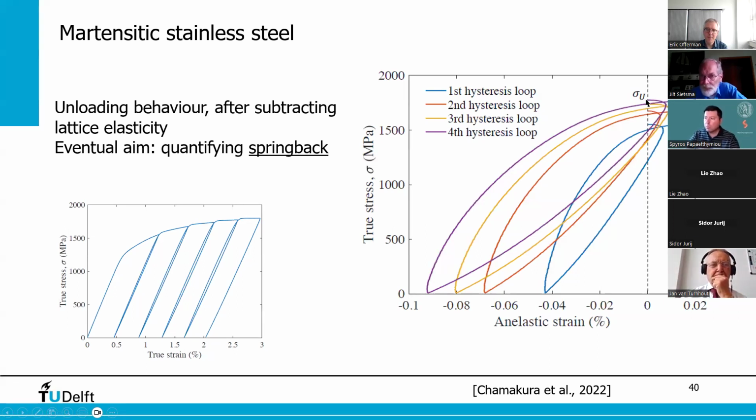Well, a few things. One is, in the beginning, when you start unloading, the strain still increases, but does not right away decrease. And that we can understand from the Frank-Read rings around the Frank-Read source. They don't go back because they have a very low dislocation line strength. So they continue a bit, and that gives the extra strain.